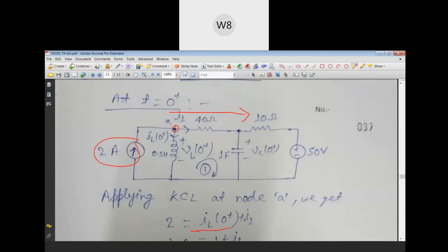Okay. So what happens here is, let us try to interpret what is happening physically now. So this current source starts pumping 2 ampere current into the circuit. Now since the current through the inductor has to be 1 ampere, the inductor continues to allow only 1 ampere current to flow through it, and with the same direction. It neither changes the direction nor the magnitude.